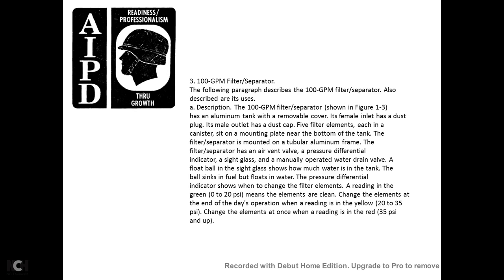The filter separator has an air vent valve, a pressure differential indicator, a sight glass, and a manually operated water drain valve. The float valve with the sight glass shows how much water is in the tank. The ball sinks in the fuel, but floats in the water.